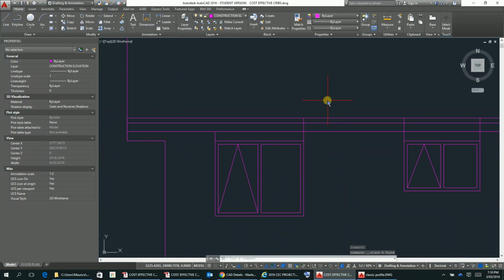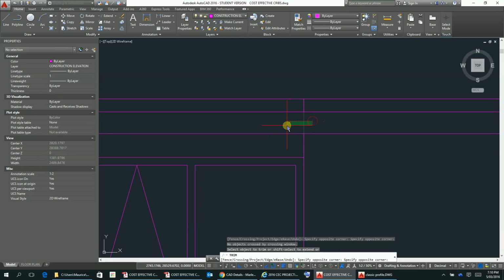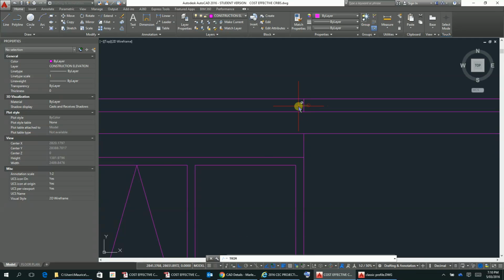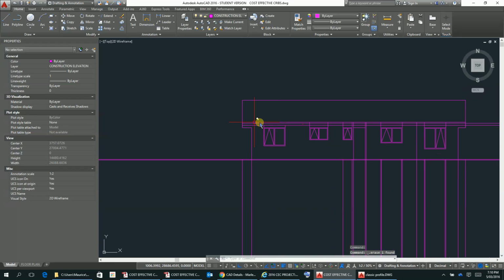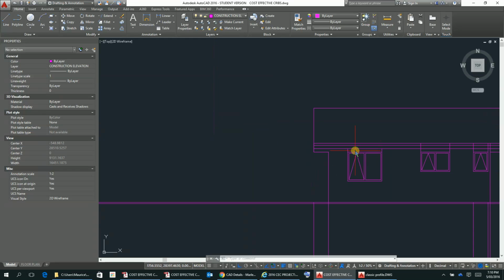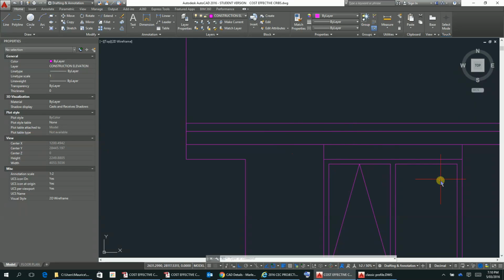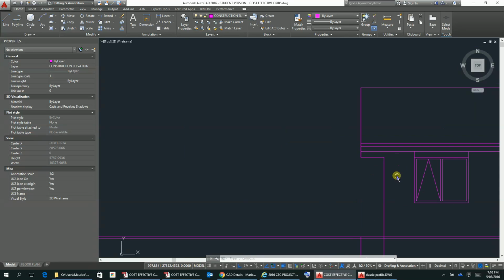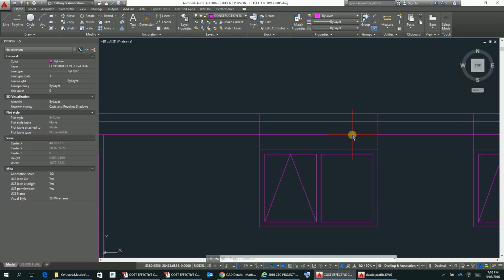Okay, so now let's TR to enter for our trim, and perhaps I should do that, which is going to select all of the line. Oh, that's not going to be trimmed there, that's just going to pop out of there. Delete. So that's getting our windows done. This here's our spouting in here, and this is the bottom of our fascia board there with the soffit, and then in here is just a little infill area, so we can get all that sorted.